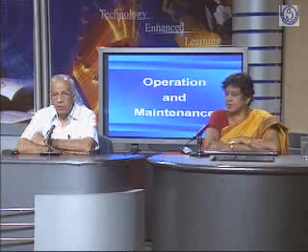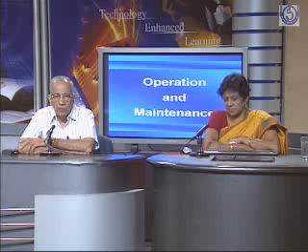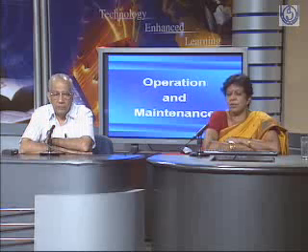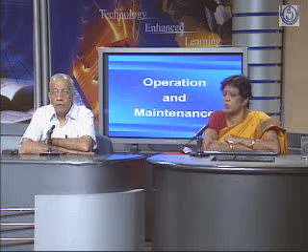Now, if the transformer is not overloaded, I am asking this question because in HVDS you provide a large number of transformers, with say 4 or 5 houses clubbed together and fed by one transformer. Now, what would be the failure rate of these transformers, because the maintenance will become absolutely unmanageable. Yes, if the maintenance is more and repair requirements are more. Well, up till now, whatever transformers have been installed, because they are not being overloaded, and the LT faults are much less. Most of the transformers fail on LT faults. Yesterday we had discussed the transformer failure.